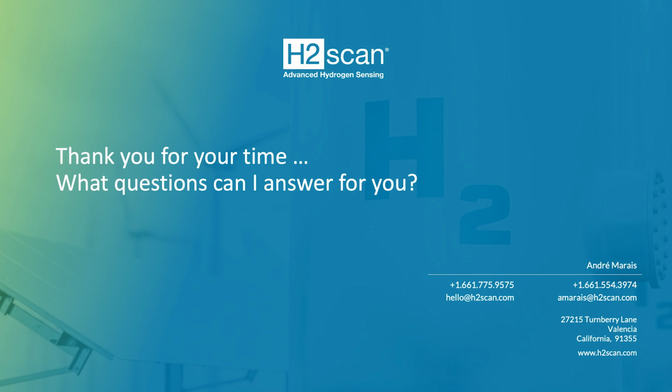So I'm going to start with Jeff G here. He said that earlier you mentioned H2 increasing and H2 decreasing. Can you speak a little bit more about this behavior? He was under the impression that H2, once dissolved, remains dissolved in the oil until degassing. Yes, H2 does dissolve, but no, it doesn't stay in that condition permanently. A few things will affect it.